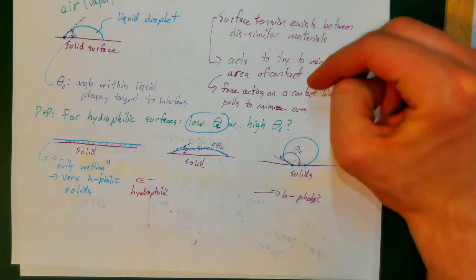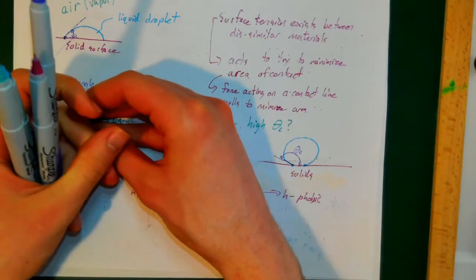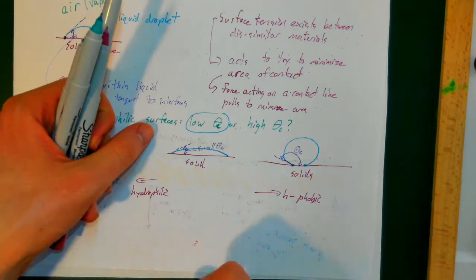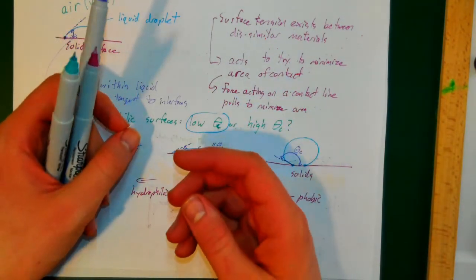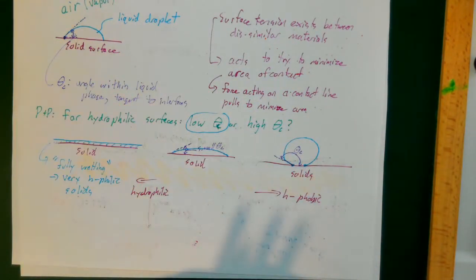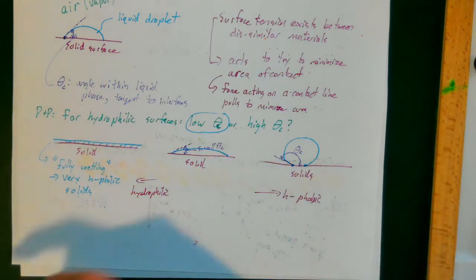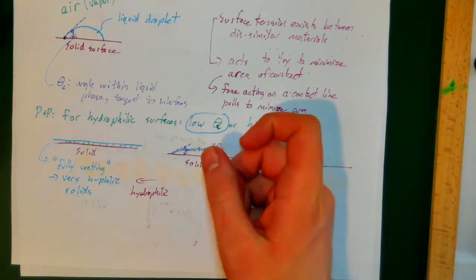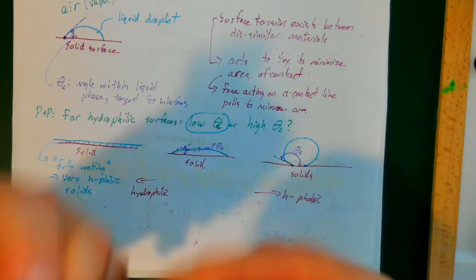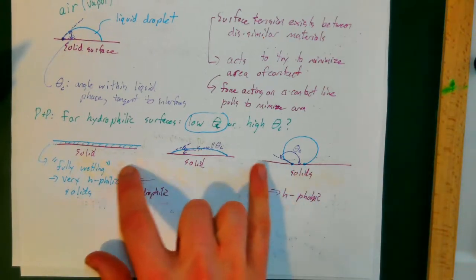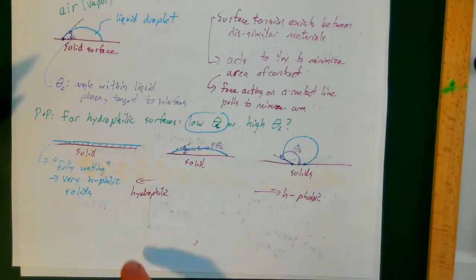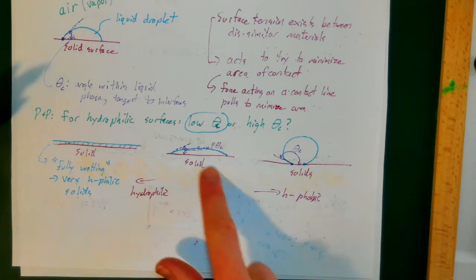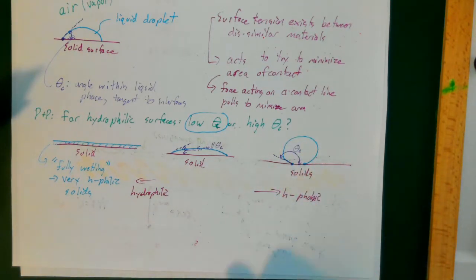You can look at the type of polymer, look at the contact angle, look up the molecular structure, and it's clear as day. It's almost down to what fraction of the bonds are carbon hydrogen or carbon carbon versus carbon and something more electronegative, and you can pretty readily predict which ones are fully wetting, and which ones the material would sort of bead up on.